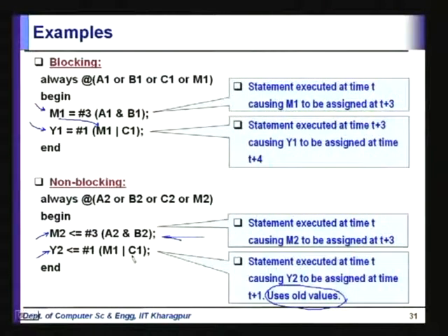So what difference does the position of this delay make if you put it in front or in between? If you put it in the front here, hash 1 y2 less than equal to this thing, then the evaluation of y2 will start after time t plus 1. See, here the evaluation has started here, but the thing that is to be assigned is computed after 1 time unit.